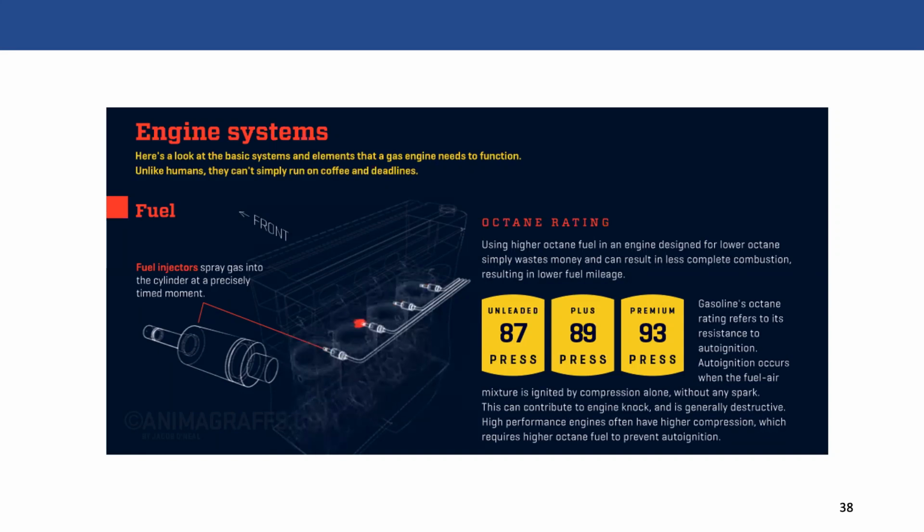And so it's a pretty big misconception that there is a correlation between performance and efficiency and octane rating. That's actually not true. As long as your engine is compatible with any of these fuels, then you're essentially going to be getting about the same efficiency.